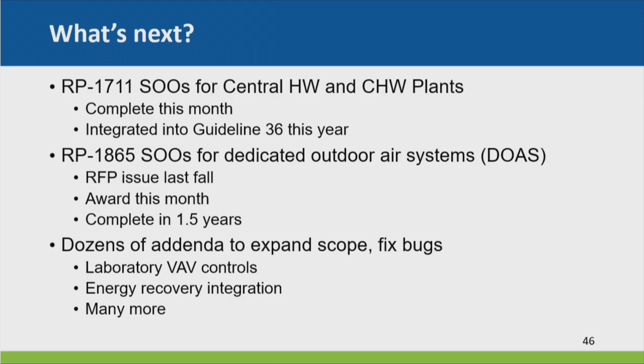We have one that we're about to issue on laboratory VAV controls. Traditionally, laboratories have the controls done by the air valve guy, the Phoenixes and the AccuValve and those kind of guys, because they have their own proprietary system. But then you end up with two systems in the laboratory, one for airflow control and one for temperature control. Well, this puts it all in the building automation system, so we don't need those guys anymore, and you can do everything with the lab controls, so it can be less expensive and work better.